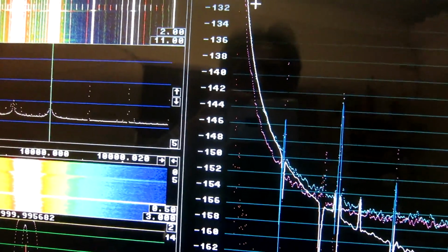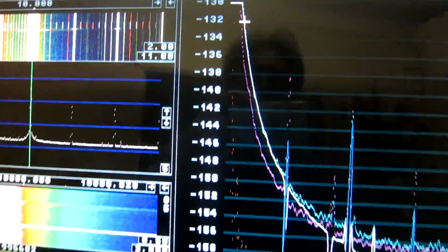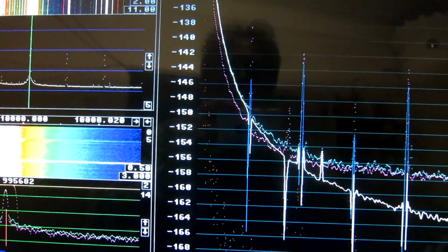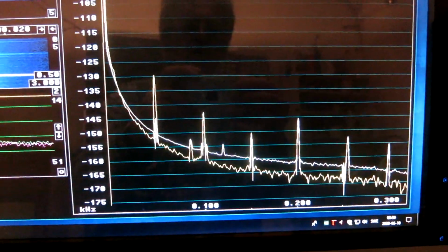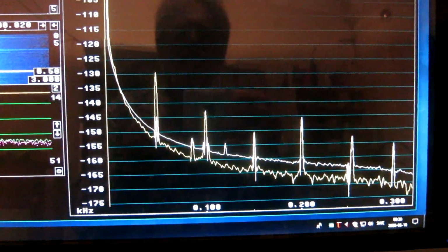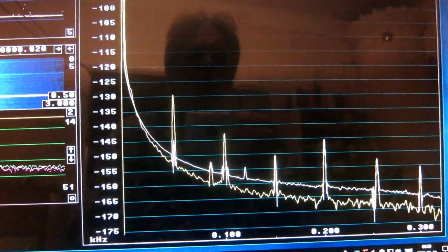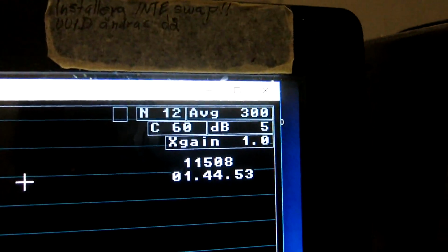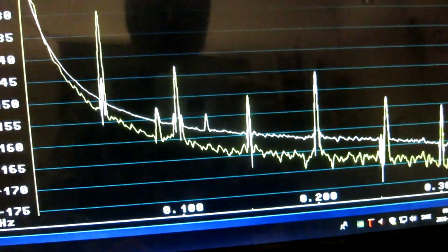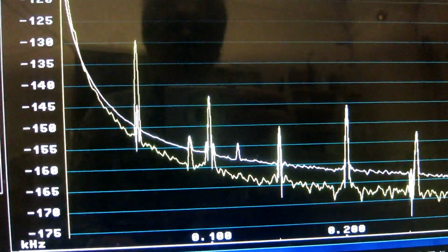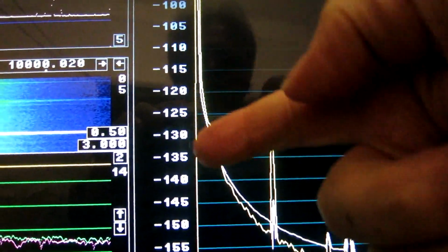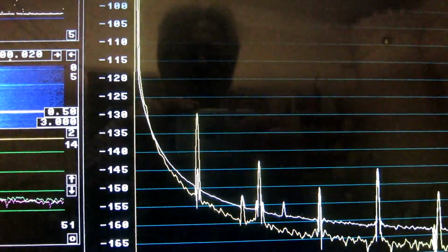So I can read closer in frequency. I have changed the scale parameters for 5 dB per division and starting at minus 60. I set those things here. And then I save 3 more images, so look for the details in this region with the pixel editor.